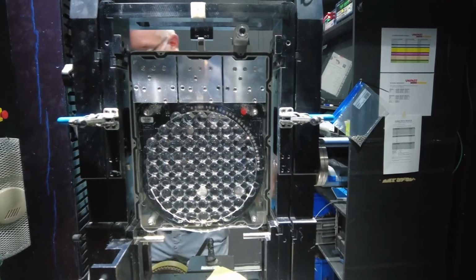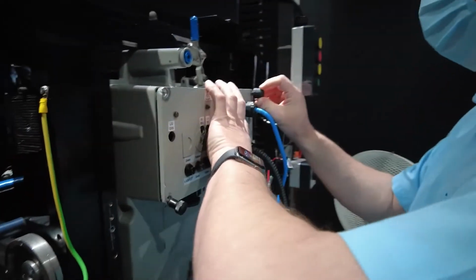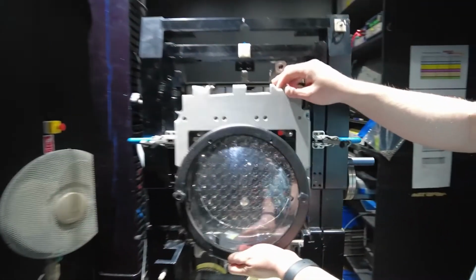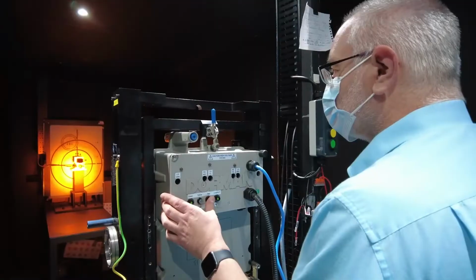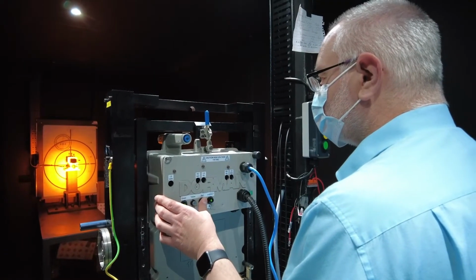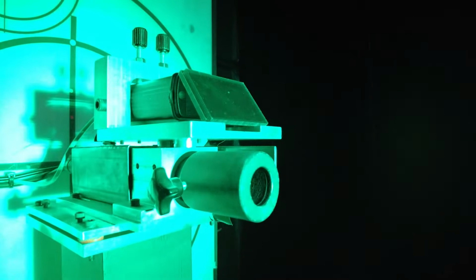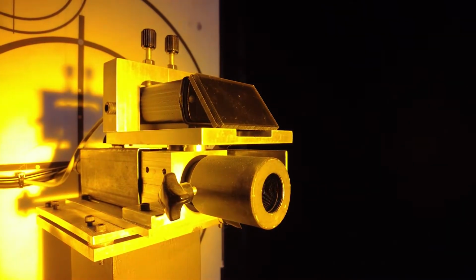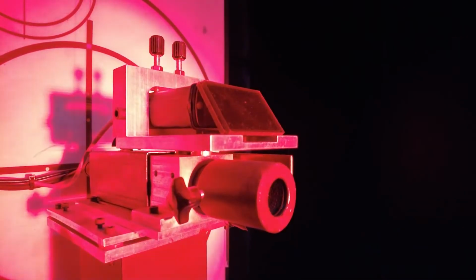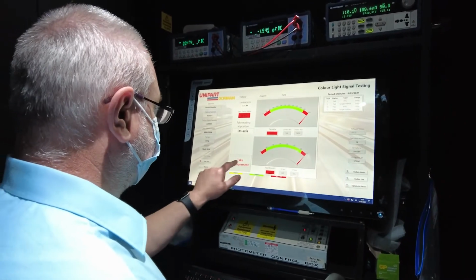So these are the components that emit the light. We look at whether we need a lens. We look at the housing and how this fits together from a mechanical point of view. We then have to go into the detailed design process, which involves placing the components precisely on the circuit board, looking at the optical design to understand where the light is going to come out. We look at the brightness levels, we look at the spread of the light output.